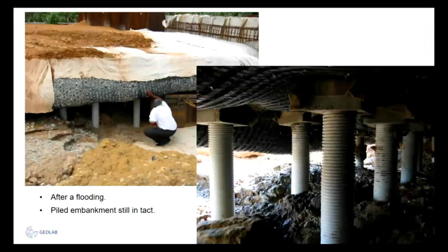That is because underneath this reinforcement there is often a working platform consisting of a layer of sand to make it possible to install the piles. And that gives a consolidation of the soft soil underneath. The result in many cases is like this, a gap underneath the reinforcement. And if we would like to do research on this subject, then we need to be able to model that the soil disappears. And in many subjects, this is an issue.